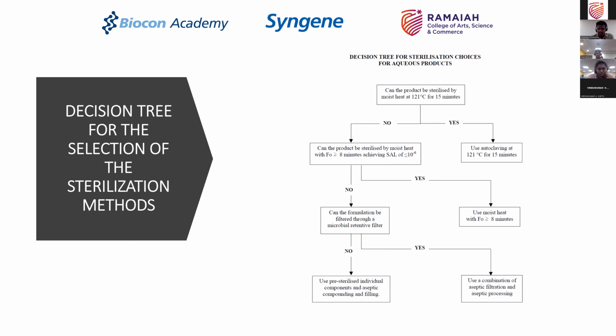So let's say you were making a suspension, but the suspension is formed only when you combine two components together and add an API to it, right? In that situation, your individual component number one, which is a liquid, you could still filter, sterilize it, and transfer it to the tank. So your tank is sterilized or made bioburden free. You have a filter which is sterilized, and then you transfer this liquid from tank one to tank three.